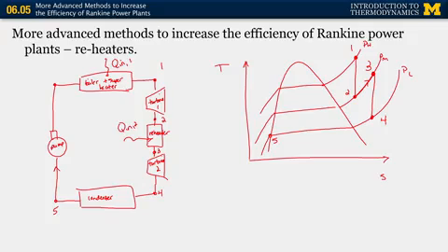And then we're going to isentropically pump the fluid to a higher energy state. And here you need to be careful. Go past that middle pressure, because remember, we have to be at the entrance to the boiler and superheater, which is on the highest isobar in the system. So that's going to be state 6 and state 6 here. Okay, so what we see is we have heat transfer that occurs here, and that's heat transfer 2, and then we have heat transfer that occurs here, that's heat transfer 1.